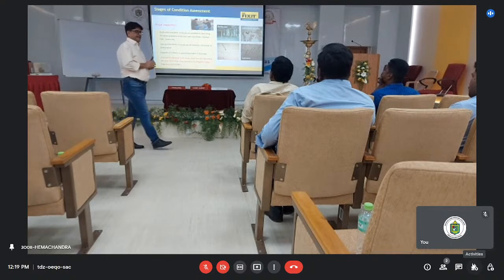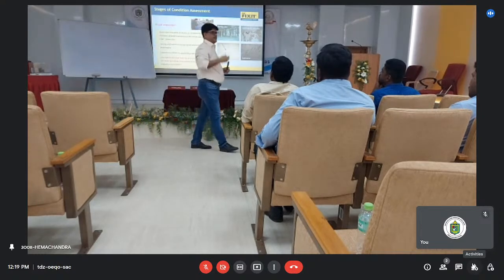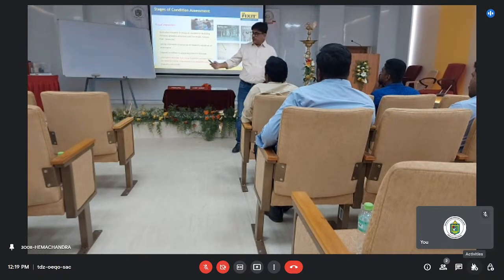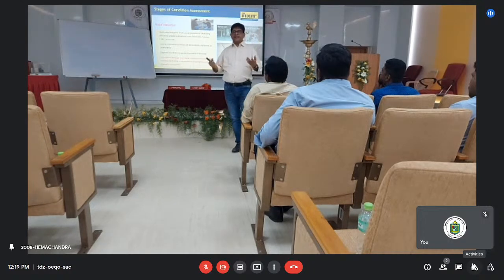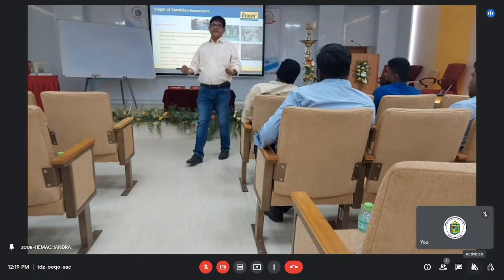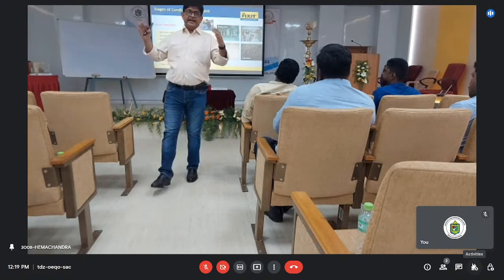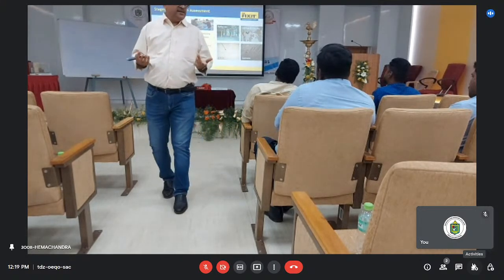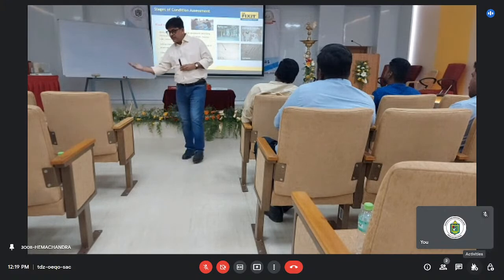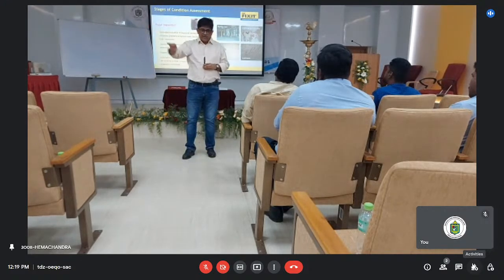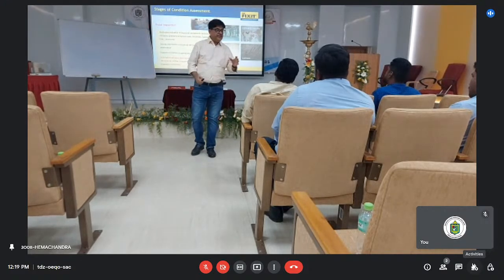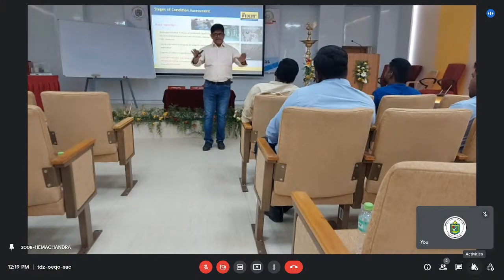Now, depending on the areas, what is the serviceability? What kind of things are happening over there? If the water is leaking, how long has it been coming? Is it coming only during the rainy season, or throughout the year? That will give you the thought that yes, only when the water table is going up is the water coming. Then it will give you an understanding whether we are standing in a dry basement or a wet basement.